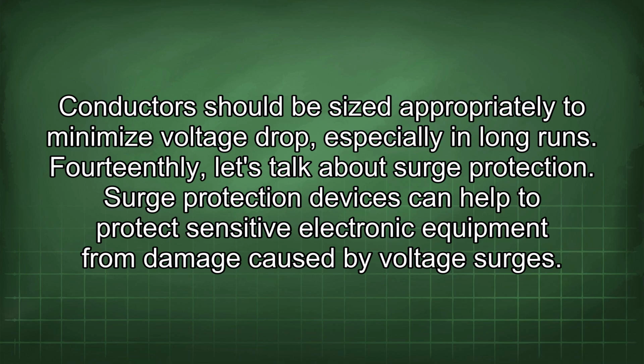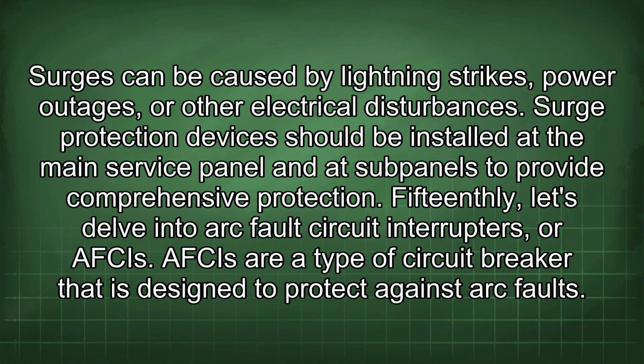14thly, let's talk about surge protection. Surge protection devices can help to protect sensitive electronic equipment from damage caused by voltage surges. Surges can be caused by lightning strikes, power outages, or other electrical disturbances. Surge protection devices should be installed at the main service panel and its subpanels to provide comprehensive protection.